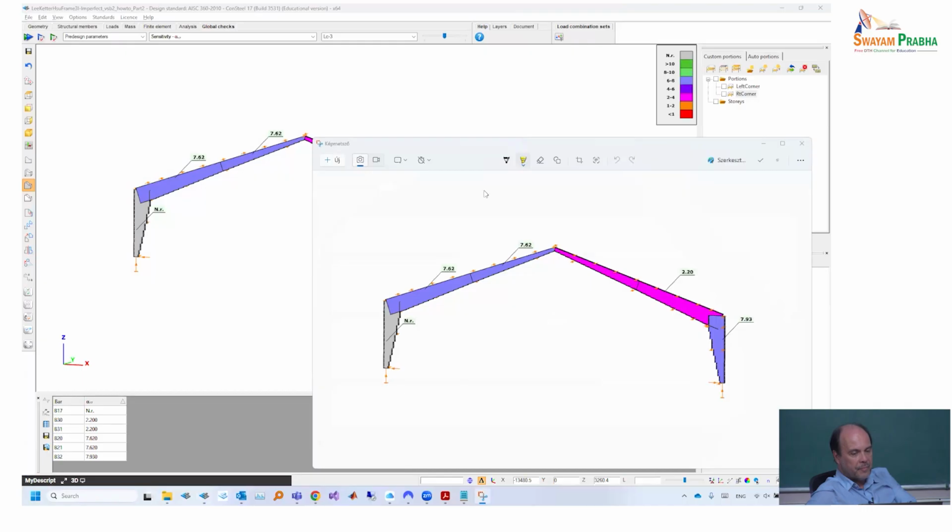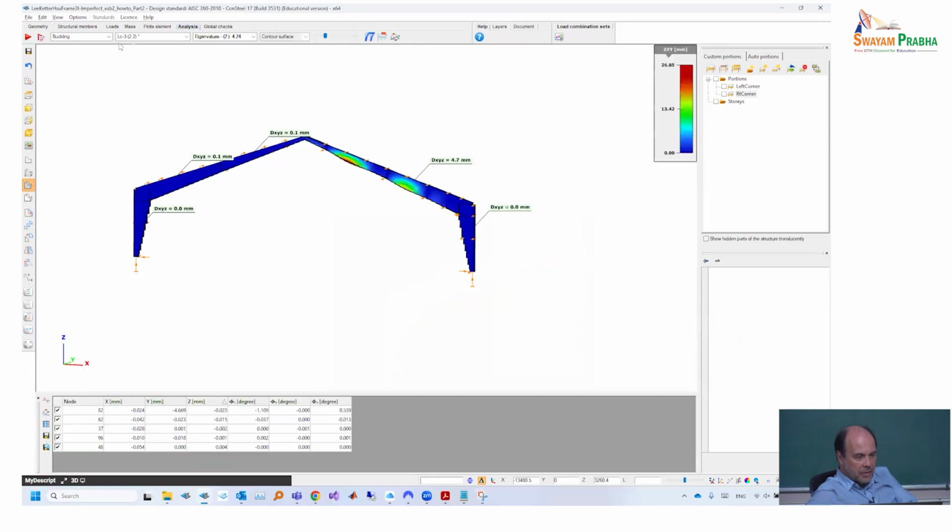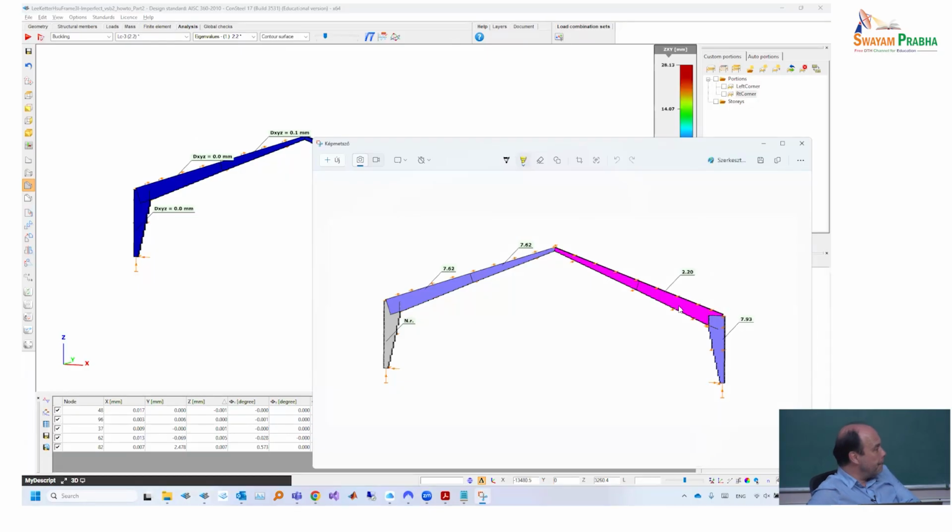Okay, so this is my map. I come back to analysis, buckling, load combination 3. Generally your map has different values at different points, and that's a bit misleading. If it's run for one combination only, then it works well. Then it really gives, for that given combination, which mode was assigned to which members. Once you run it for more combinations, what it shows starts to be a mess. It gives you a certain feeling that at the end of the day there is no member which has got nothing, but it's not very relevant.